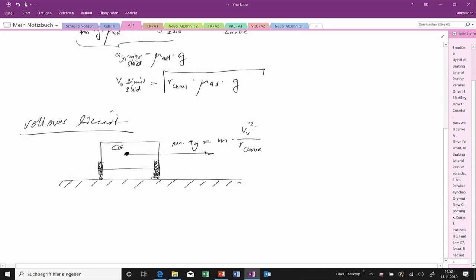And so this force, this lateral force, is acting at a certain height above the ground, and this is h. It's the height of the center of gravity above the ground. So this gives a control arm, or a lever arm, and so we have a force on a lever arm. So this is a torque, and there is of course another torque. So if this is pulling on this graph to the right, because I'm going into a left curve, this here is a critical road contact. So this will be the pivoting point for rollover.